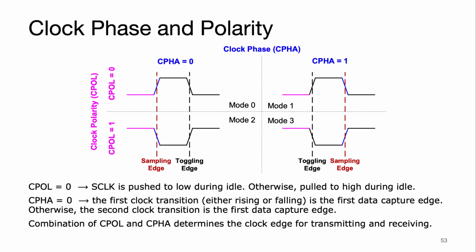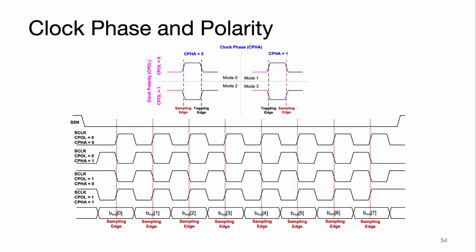Basically, the thing to take away here, and I think I said it backwards a few times, is there are 4 configurations. Is the clock positive or negative? Are you sampling on the rising edge or the falling edge? That's it. And here's just another way to look at these diagrams. Here's where the sampling has occurred, and then you have 4 different variants of the clock signal that can occur for that same sampling edge.